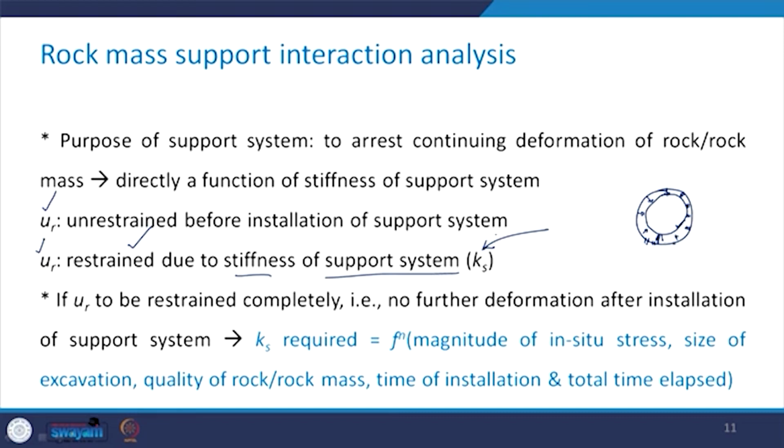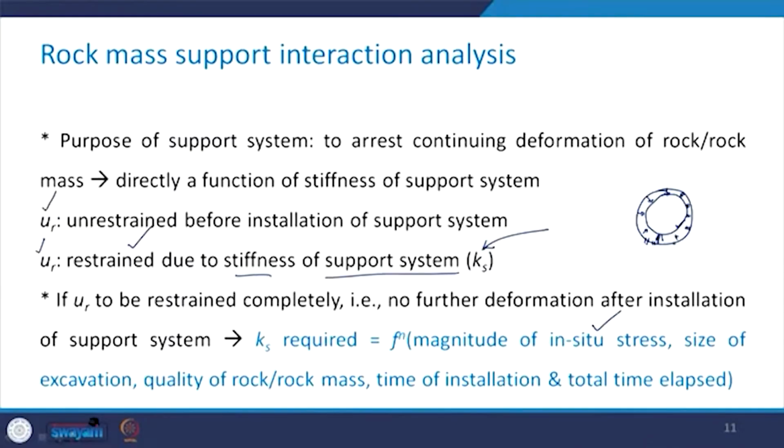That is, there is no further deformation after the installation of the support system. Obviously, the stiffness of the support system Ks which is required will be quite high, and therefore, the required Ks becomes a function of the magnitude of in situ stresses, size of the excavation, quality of the rock or rock mass, time of the support installation, and the total time that has elapsed.